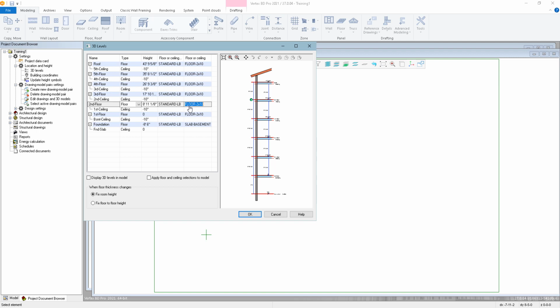If a height level is changed after you start modeling your building, then all of the objects that are constrained to that level will adjust with it, which makes it easy to modify building heights later on. To change the height of an individual layer, simply change the value in the height field for that level in the list view on the left side of the dialog box.